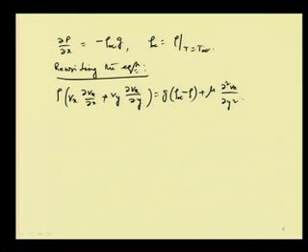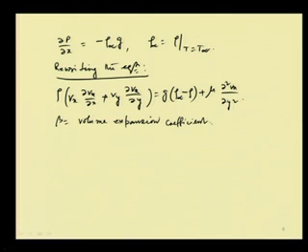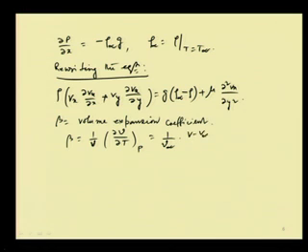Okay. Now, what we will do? We will define a terminology called beta. It is nothing but the volume expansion coefficient. Beta is equal to 1 by V, where V is the volume, into del V by del T at constant pressure, that we know. This can be written as 1 by V infinity, where V infinity is the volume at T equal to T infinity, into del V, which is V minus V infinity, the change in volume because of the change in temperature, by the change in temperature T minus T infinity.